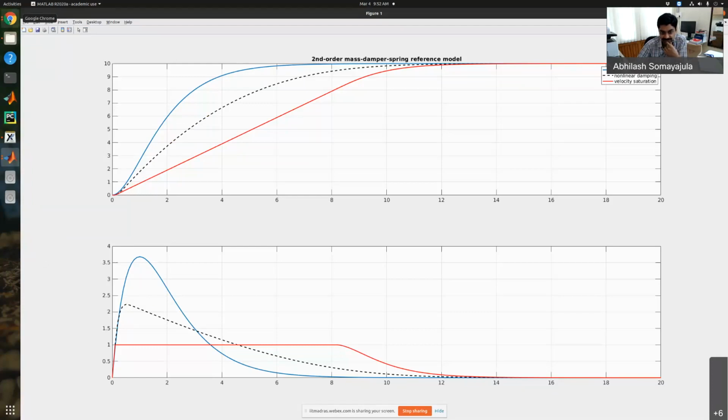The velocity is now relatively lower. Yes? So what went to 3.6 now only goes to a maximum of maybe 2.3, right? Now, sometimes even that might not be achievable. That might still not be a velocity which physically represents the limits, and the velocity can no longer be more than 1 meter per second, let's say. In which case, we may want to saturate the model. And when we saturate the model, we are restricting the velocity to be maximum 1. It cannot be any more than 1.